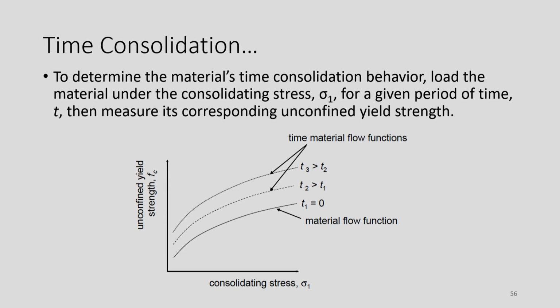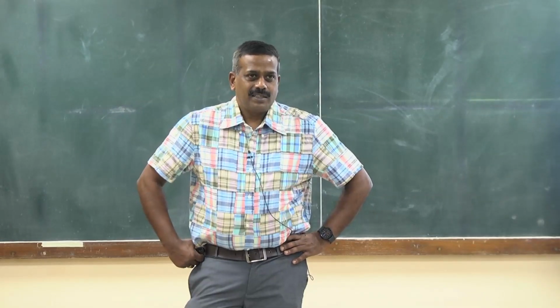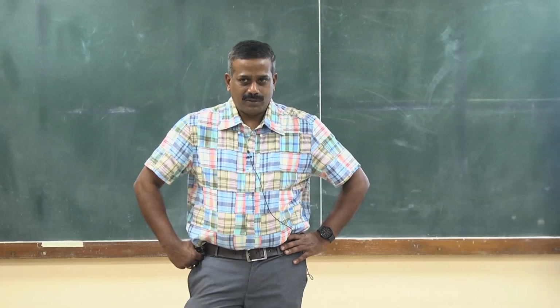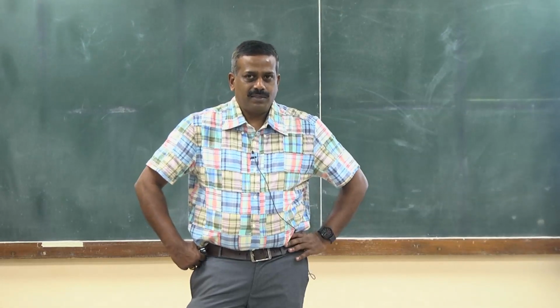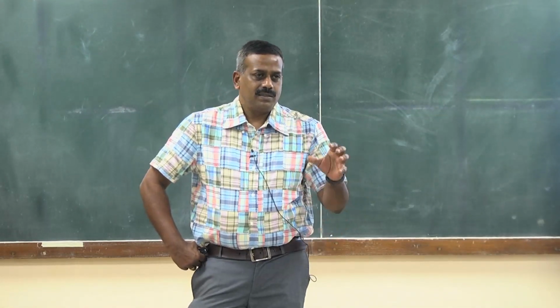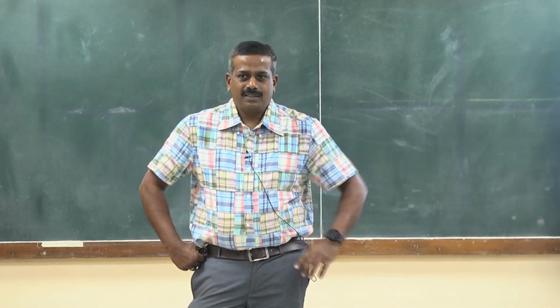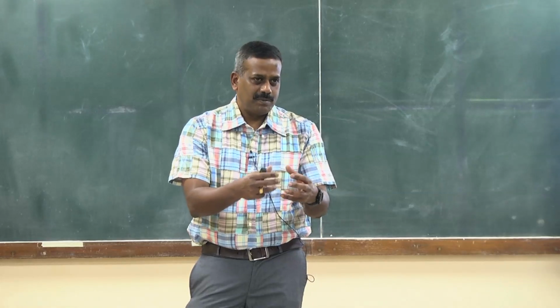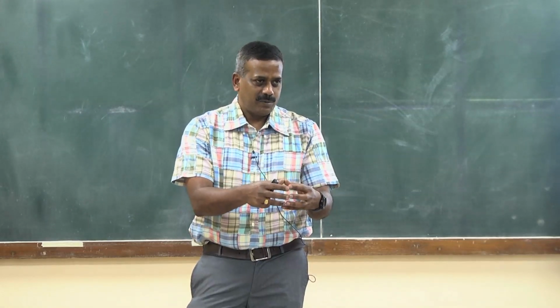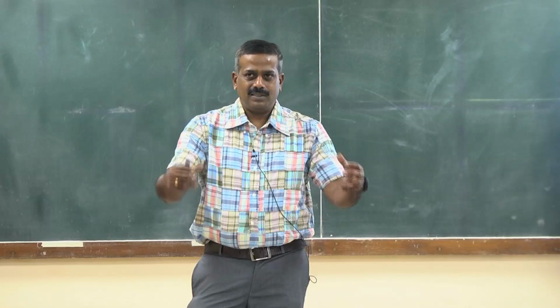Have any of you learned about liquid bridging, solid bridging, etc. between powder particles? It's very common in food powders. If you're working on food, just Google and see deliquescence. Deliquescence is surface melting of food powders. It's common in food and pharmaceutical powders too. When the powders absorb water, the surface starts melting, and when it starts melting, it forms bridges between particles. It forms liquid bridges, then it turns into a solid bridge, then caking occurs.